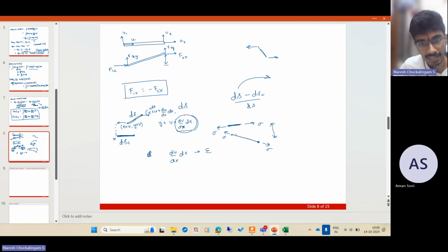So if you just consider linear elastic, if you just consider linear displacements, only the projection will matter, and this will develop no vertical resistance. Okay, or even simpler, let's just put 3 nodes subjected to some force P, and say it is a truss.